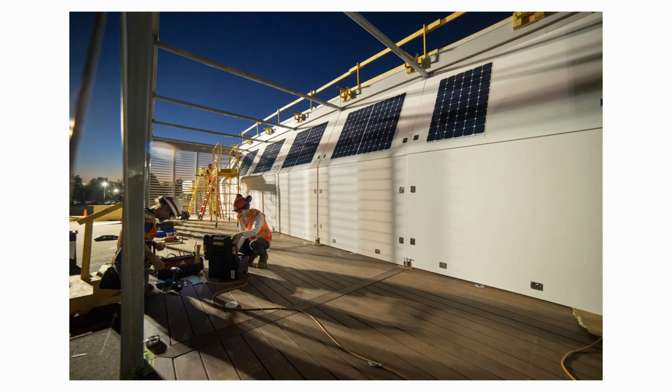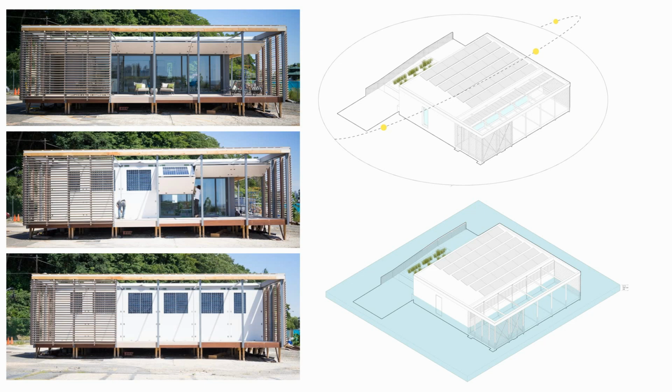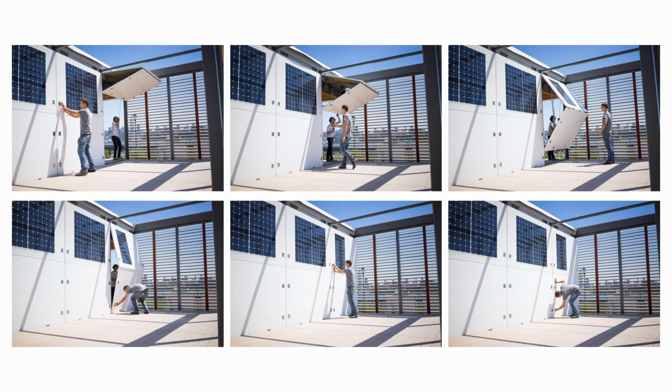The idea then is you can see here the hardware on these panels. These were highly engineered. The top panel is different than the bottom panel because there are different requirements. It's lighter at the top so that it can lift more easily, and the bottom is heavier so that it's more structurally sound so that it can take the water loads. In normal use, the shutters are up and they are sun shutters, sized so that we were letting the sun in the winter when we wanted and blocking it in the summer with typical passive solar design. And then if a storm was coming, you would close them down from the outside and leave.